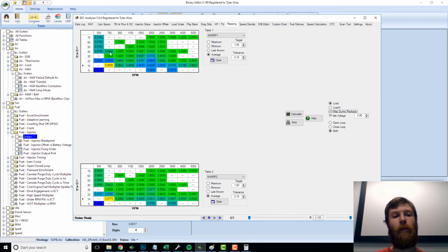So when I was idling, which was around 700 RPMs, and that's a very low load, you notice that it's making more adjustments. Then as my RPMs increase a little bit, it's not having to adjust quite as far here. And then it looks like I'm running pretty considerably rich here. On some of these slightly higher loads, things look like they're actually pretty accurate. So this is the kind of setup that you have to go through to understand this.